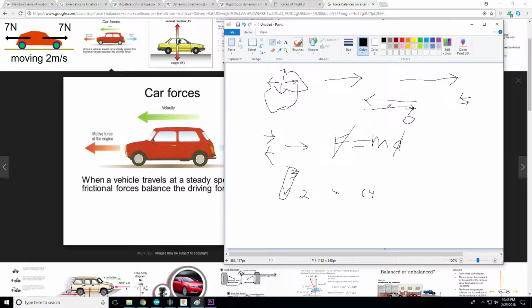Add a bigger spinner so the air slips further over it, to minimize drag, but put a giant motor on it that gives me a lot of forward thrust. So I'm minimizing my drag and maximizing my forward thrust. That will lead me to a very high maximum speed. And obviously, in this case, pick the right prop for that large motor.